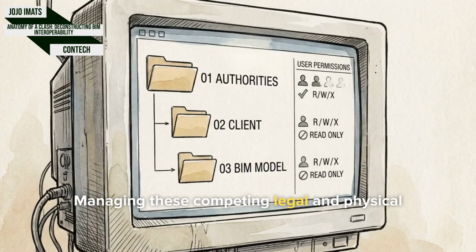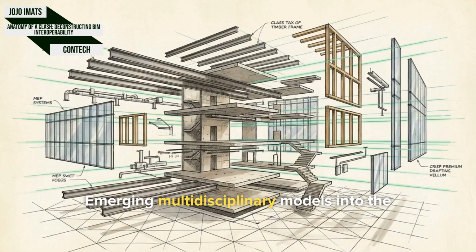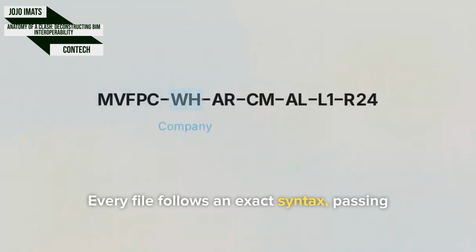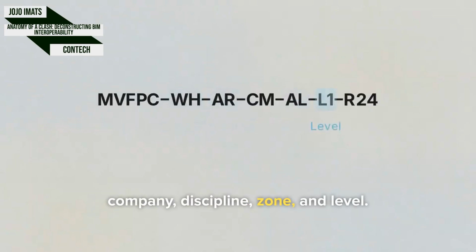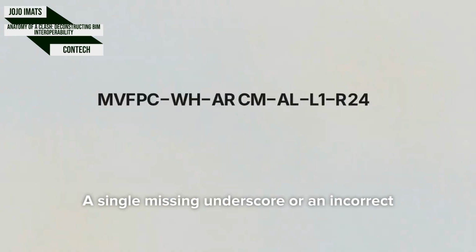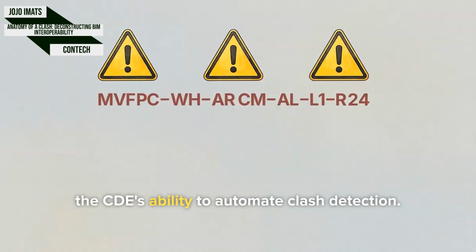Managing these competing legal and physical constraints requires a centralized operational framework, the common data environment. Merging multidisciplinary models into the CDE demands absolute data hygiene to prevent system-wide indexing failures. This layout details the required file naming standards. Every file follows an exact syntax, passing sequentially through variables for project, company, discipline, zone, and level. This structure is fragile. A single missing underscore or an incorrect subdiscipline abbreviation immediately breaks the CDE's ability to automate clash detection.